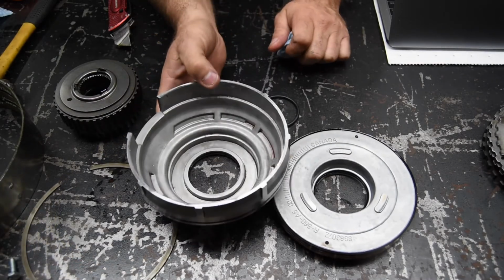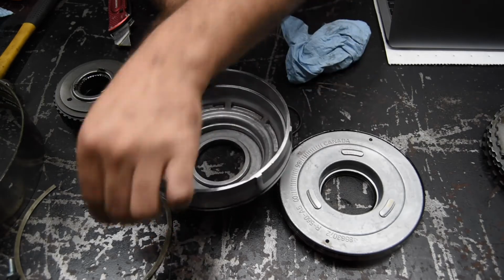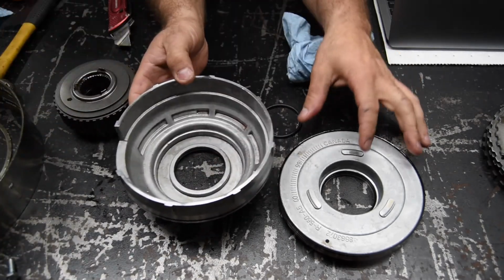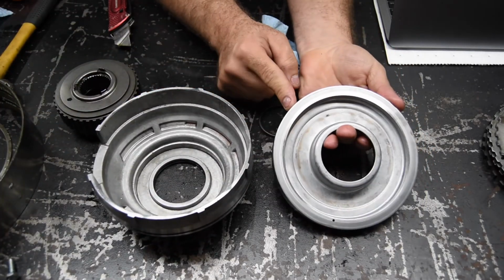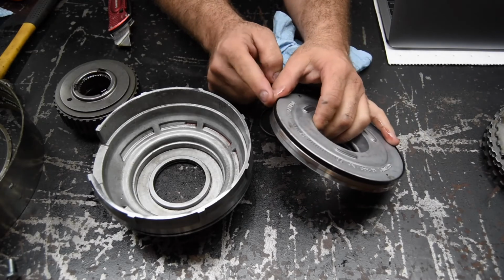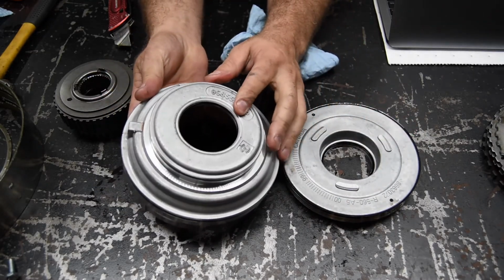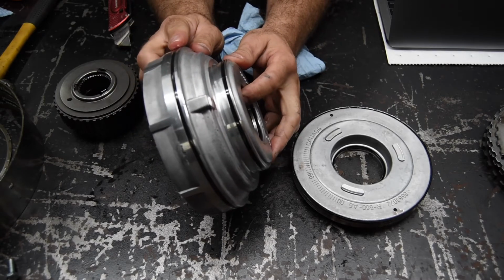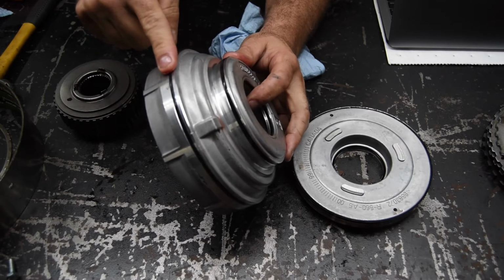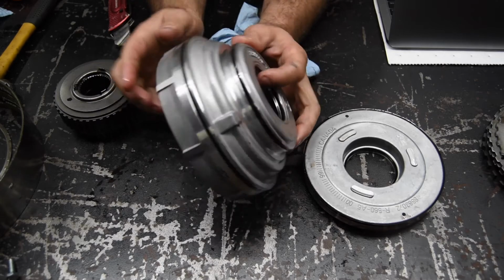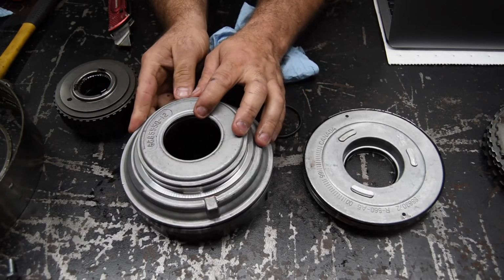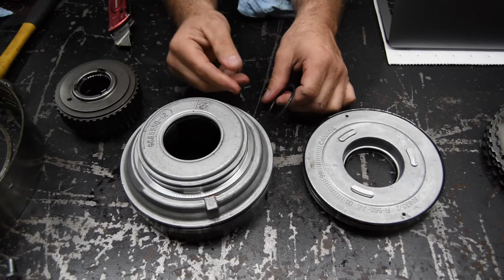All right, we're back on the table, and we have various components here that we're going to take a closer look at. So the first thing we've got is the piston that came out of the reverse input clutch, and it's got its seals on it. And this is our low reverse piston of the transmission. This one actually has 3 seals on it. It's got a seal here, seal there, and a seal right here. And we can get to see the different types of seals. So I don't have a bonded piston yet.